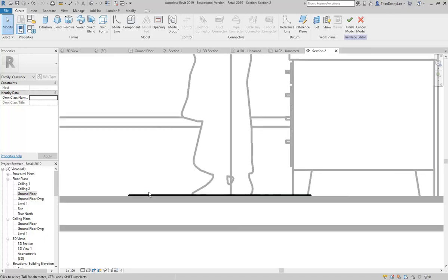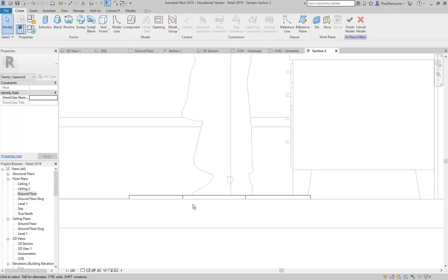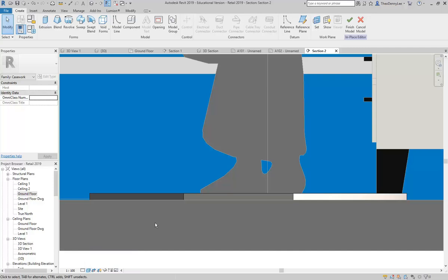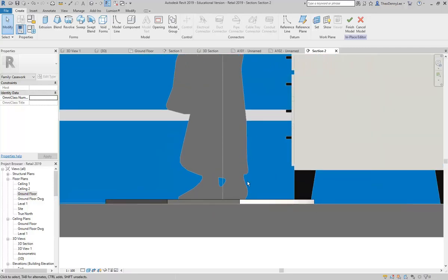And to see the lines clearly, I'm going to turn the line weights off by clicking on the thin lines button at the top, and then I can see the ends. I'm also going to change the view to shaded so I've got some idea what I'm looking at. So I've got the end there, that should be the corner that's closest to my view, that corner there. And I'll just make that clear if I go back to the ground floor.